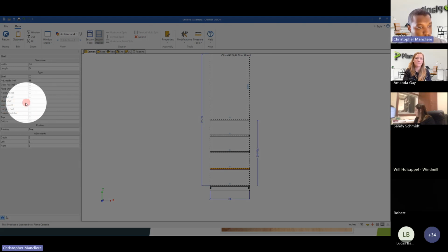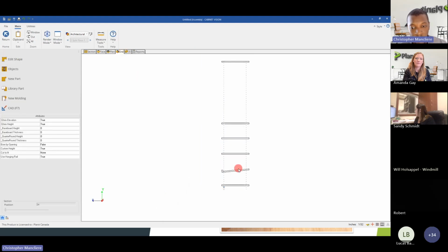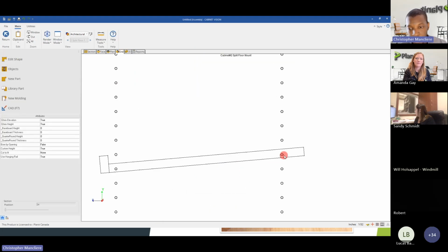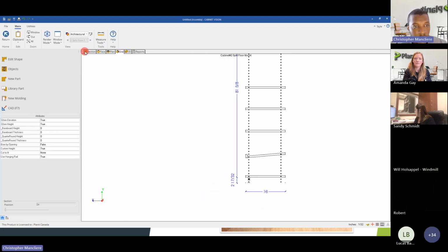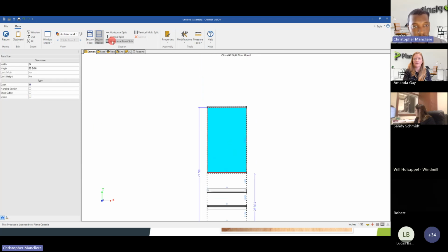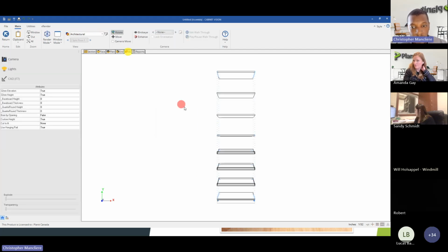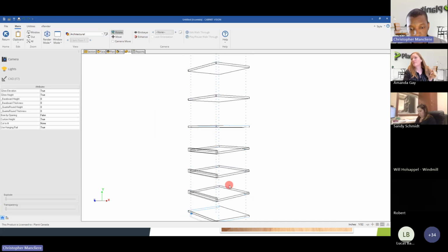So I can select this shoe shelf type, and you'll see that when I activate it on one of the adjustable shelves, they will now switch to a shoe shelf, and the notch will also be applied as well. And I can do the same thing for the other two ones I have, and shoe shelf here. And on top, I will add just regular adjustable shelf. So now I have adjustable shelf and shoe shelf at the bottom.